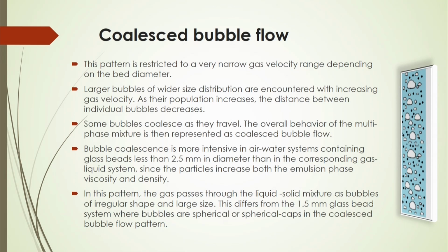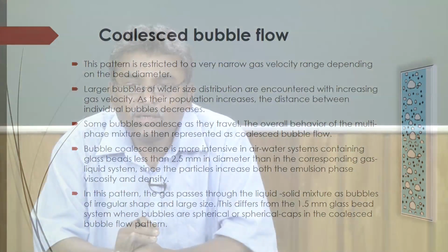Sometimes cap type bubbles will give you easier coalescence compared to other shapes of bubbles. Of course, this coalescence behavior depends on particle diameter also. For finer particles, the coalescence behavior will be higher than for coarser particles.